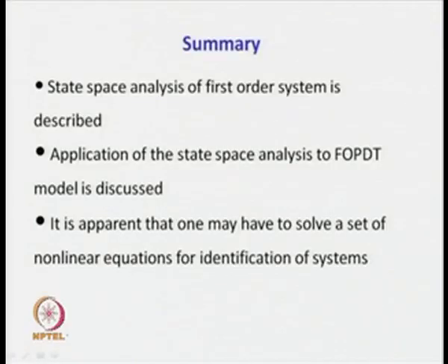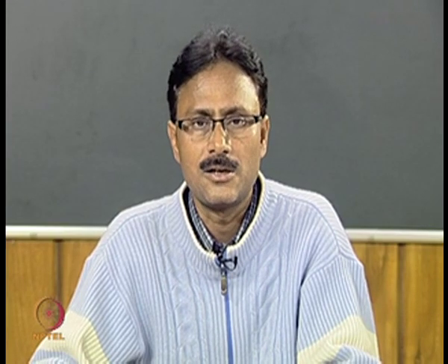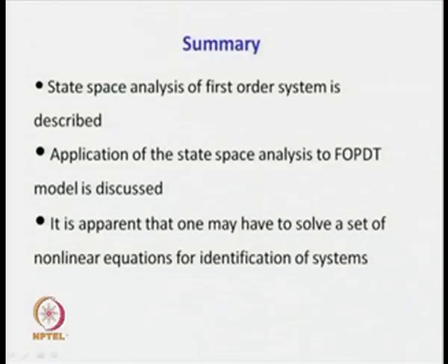What have we learned from this lecture? That state space analysis of a first order system is described, where we have been able to derive simple expressions that can be solved simultaneously to estimate unknown parameters of a first order plus dead time model. Also, we have seen that application of the state space analysis can be extended to identify simplified models. How that can be done, that we shall discuss in the subsequent lecture.